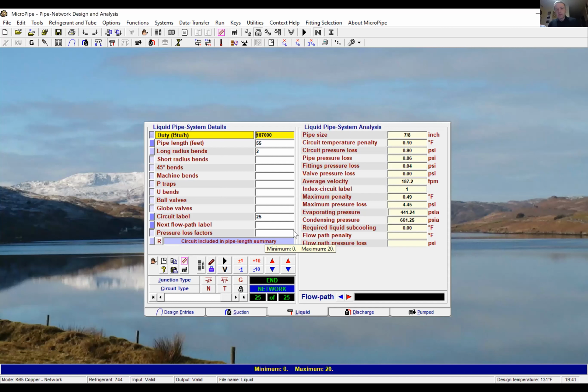Just something to point everybody in the direction. So overall, of the 11 cabinets, of the 11 fixtures that are in this system, it accounts to 187,000 BTUs. Just now I'm going to go to the discharge line, so from the main discharge header, from the rack, that line going to the gas cooler in this instance, or condenser.